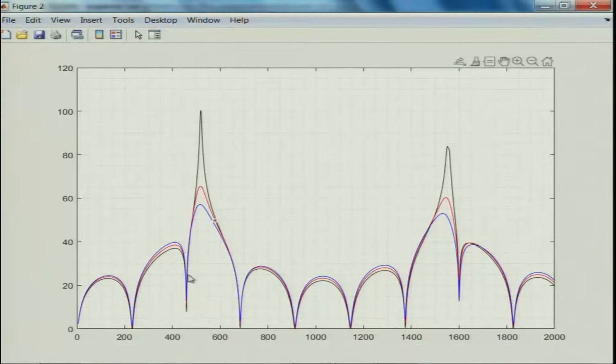Well, the effect is more prominent, isn't it? So, we get these wonderful nice results, apart from the occasional mishap because of instability. 15% porosity, 20% porosity is still a very highly porous section, but typically if you have 30% or more porosity, it is almost acoustically transparent.